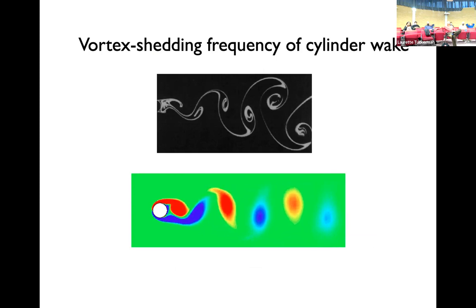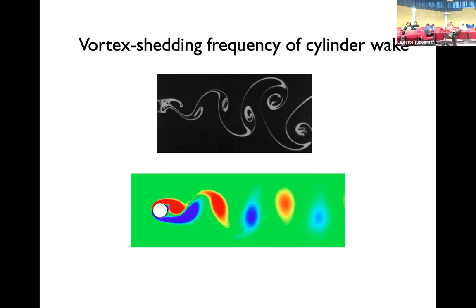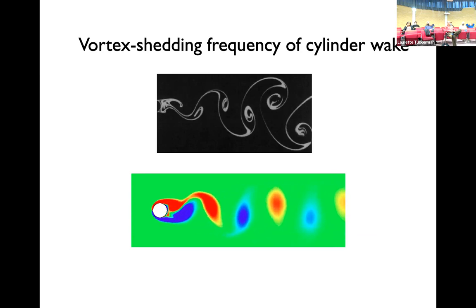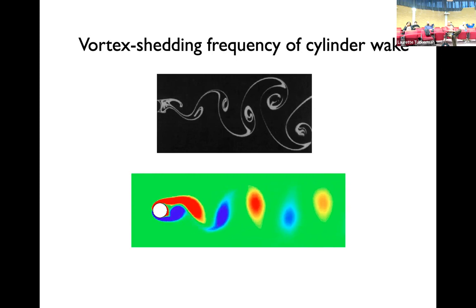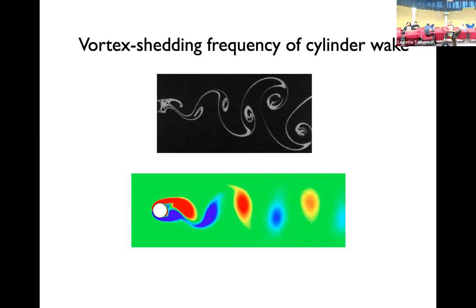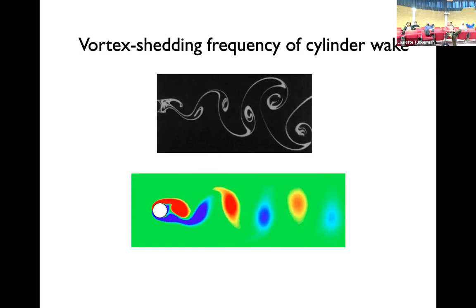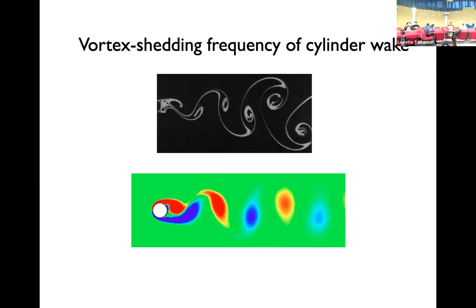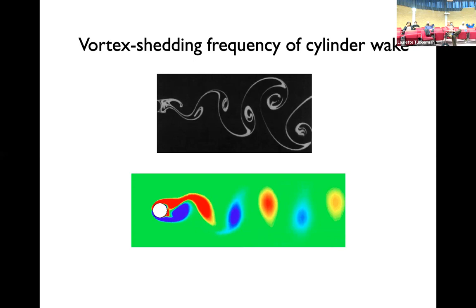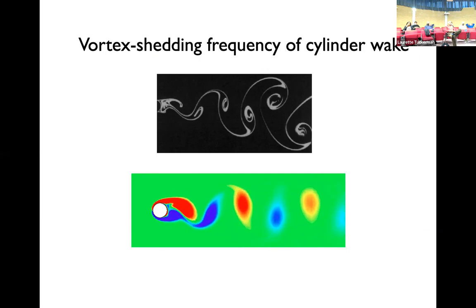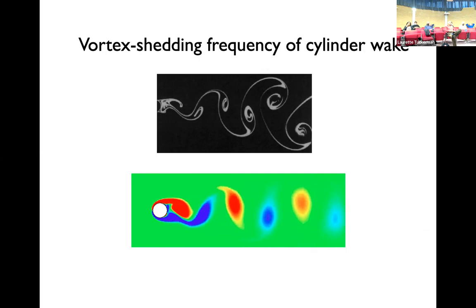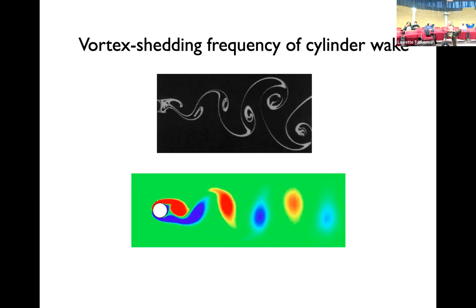So here is the flow past the cylinder. The colors are vorticity, and you see this is very characteristic. It's one of the basic dynamical problems. After a certain Reynolds number of 46, it starts to emit these vortices, called the von Karman street. It's also called Bénard. Our great ancestors, the pioneers, found this. Okay, so everybody see that, and you see that it has a frequency. Red, red, red, red, right? Okay, so the talk is about that.